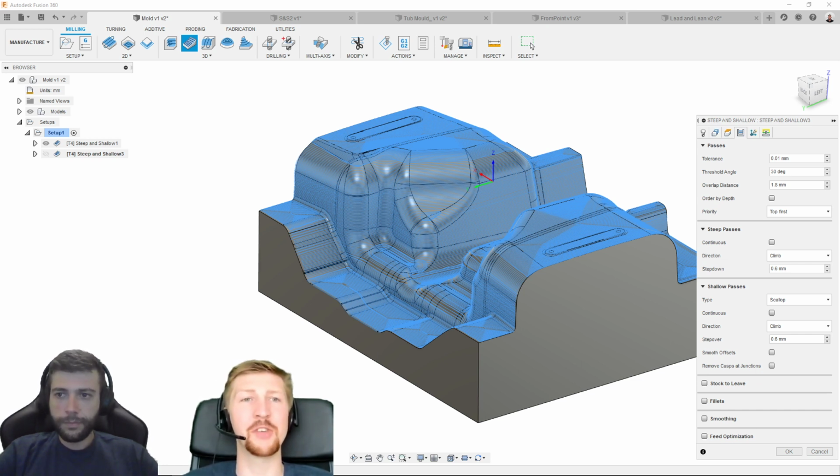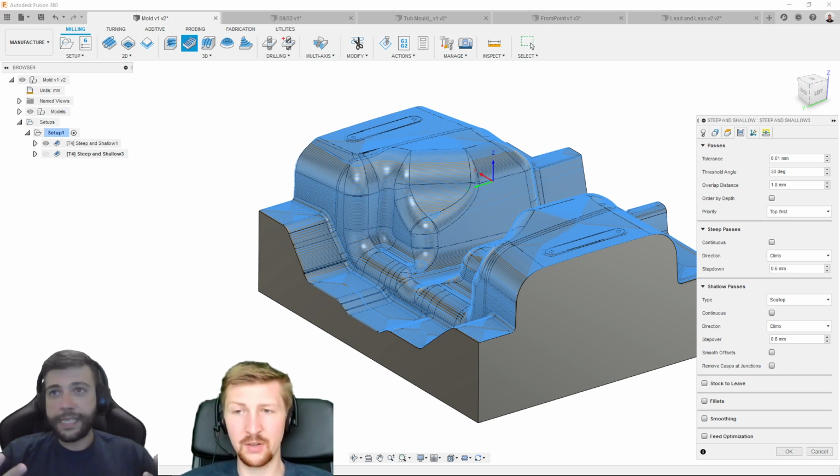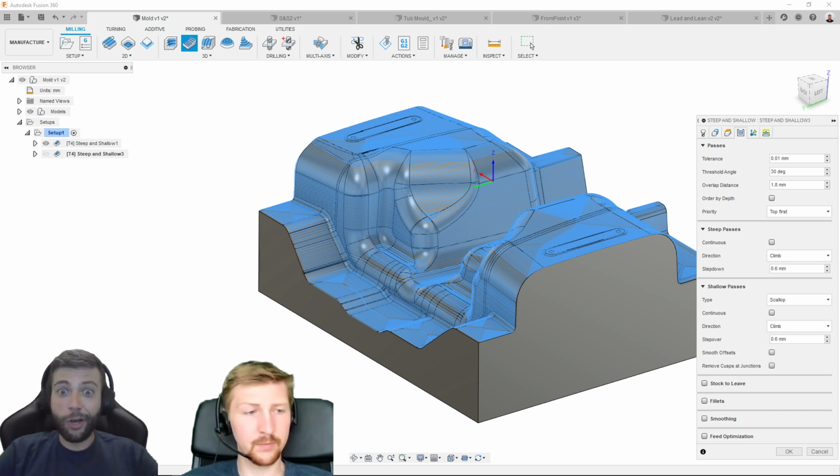It's always step down. So we're trying, on that 30-degree or 45-degree tipping point, to change from one to the other, aren't we? All the time, to try and get the best parameter to drive the surface finish. Correct. Absolutely right. It would make no sense to specify a step over on a steep wall. As you said, the concept of stepping over is completely irrelevant. If you move down 1 mil, you can go down easily 10, 15 mil.